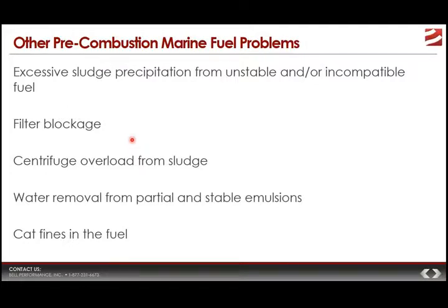That's a pre-combustion fuel problem. Remember that. Other pre-combustion fuel problems: well, this excessive sludge precipitation, we've already covered that. Filter blockage, we covered that as well. Centrifuge overload, remember that if you have a lot of sludge and asphaltene dropout, it will show up in places like centrifuges. You can very easily get water in marine fuel oil. And if that water gets in there, it can form a partial or stable emulsion, which you don't necessarily want.